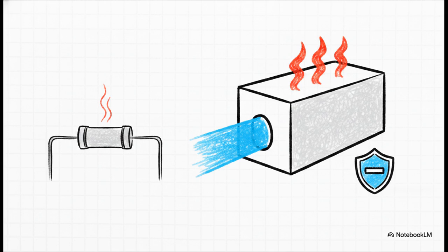For standard small electronics projects, quarter-watt or half-watt resistors are totally fine. But if you're dealing with high currents, you absolutely must step up to those larger 2-watt, 5-watt, or 10-watt ceramic resistors to prevent your circuit from overheating.